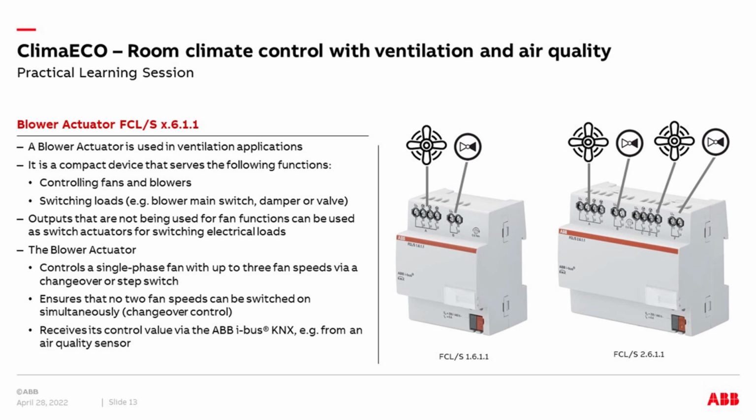So there are never more than 1 relay closed, and step switch means I close 1 relay after another. Depends on the behavior of the fan. You have to take care of this, depends on the hardware you have. And of course this component always receives the control value from the controller.